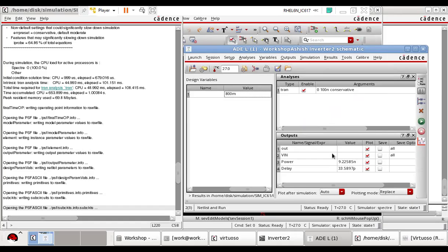Because sometimes you see in the manual of your device, whenever you get a device, suppose you get your phone or your computer, you see the manuals. You see what is the maximum possible current, what is the minimum possible current. This is because they test the device on all the possible process corners and temperatures. They tell you do not operate this device below this temperature, do not operate this device above this temperature, because of this temperature analysis only. They know that if you use your device above or below that specified temperature, you may get some arbitrary results. So that is why these specifications and simulations are necessary, right?